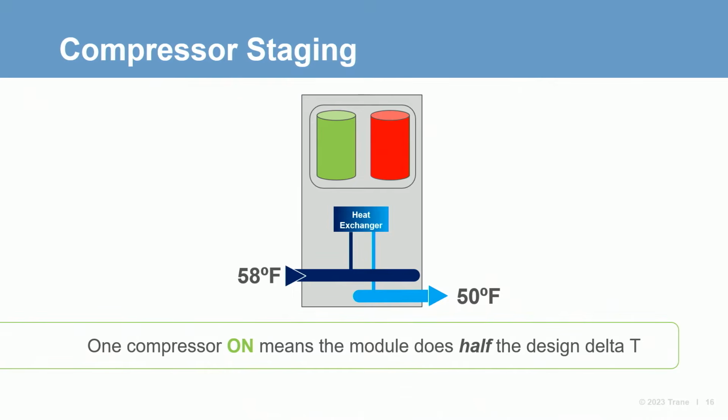With only 1 compressor running, you can see how we vary quite a bit from the leaving chilled water set point, making only 50-degree water. If the entering water temperature continued to decrease due to low loads, you can see how 1 compressor would cycle on and off to meet the decreased load the best it could, with temperature fluctuation. The real way a modular chiller bank meets varying system loads is by utilizing the multiple modules with multiple steps of control to achieve a mixed water temperature output.